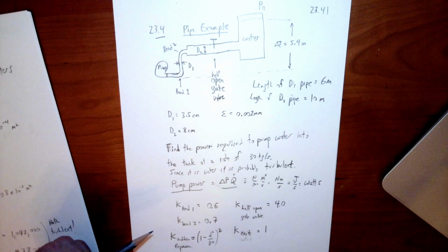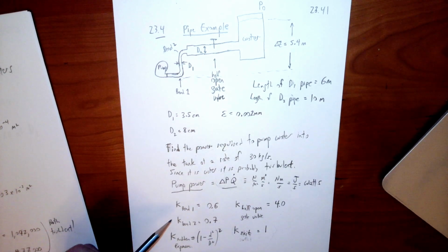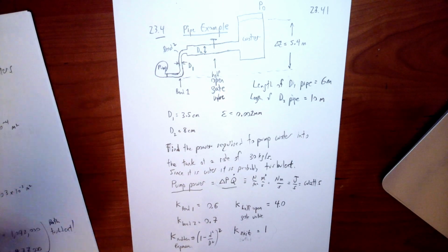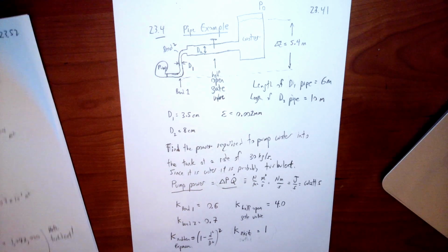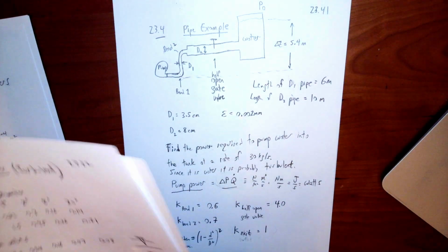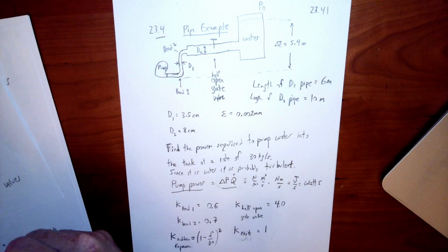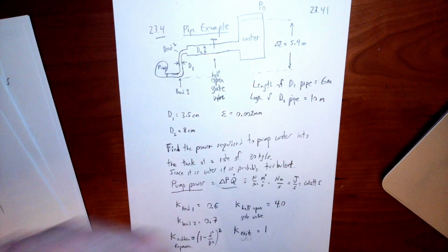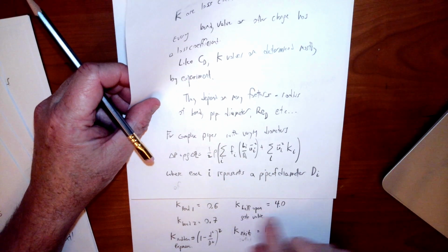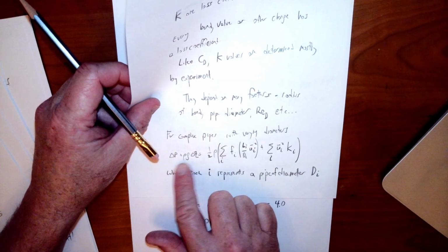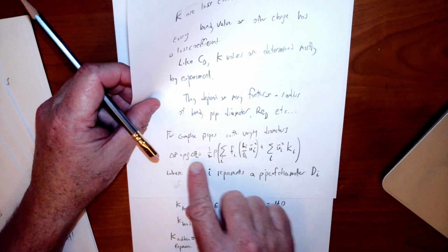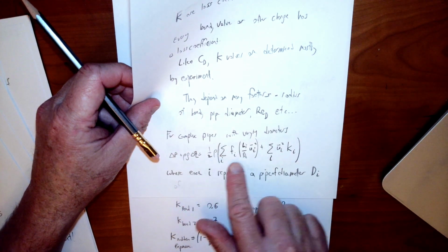So I'm going to turn this video off now, and I encourage you to go back and look at the formula that we developed to calculate the pressure loss, or the pressure needs, for a pipe of this type, and see if you can actually apply this formula. So this is the formula that we learned before. Delta P plus rho g delta Z is equal to 1/2 rho times this group.